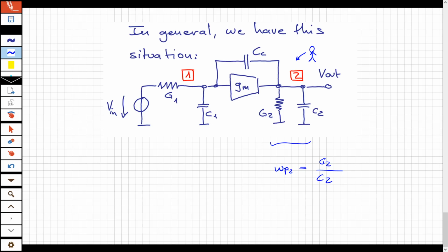But now suddenly some current disappears here in that direction. It also comes back through the feedback, and this means that the more CC you have, the lower your effective impedance goes. So the effective output conductance will rise. So you will get more stuff happening because of the feedback. And in the extreme limit, what is a CC that goes to infinity? If you really bring it to the extreme, it is a short circuit, isn't it?